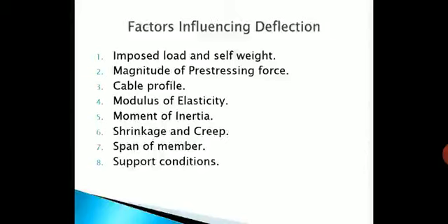Prestressing force also plays an important role in deflection, as we have noted in the previous slides. It acts as a counterbalancing force. Next comes the cable profile. As we know, we have various cable profiles such as horizontal, parabolic, trapezoidal, etc. These cable profiles also play an important role in influencing deflection.